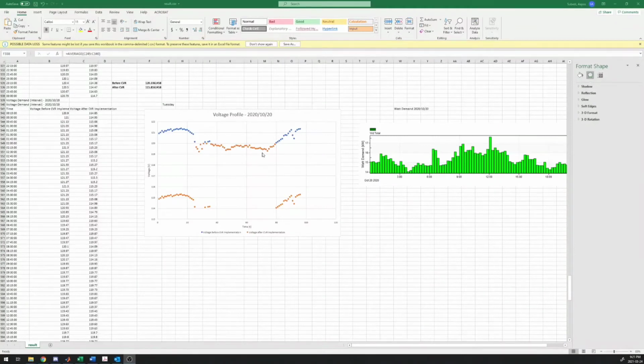From these graphs, we can generalize the trend in voltages. So the voltage is being oversupplied to the bus starting midnight. The voltage trends above 120 volts. And when it reaches the morning time, so around 6 o'clock in the morning, the voltage decreases due to the peak load. Either stays above or below 120 throughout the day depending on the demand for that day, and eventually goes up way above 120 when the demand slows down in the evening time.